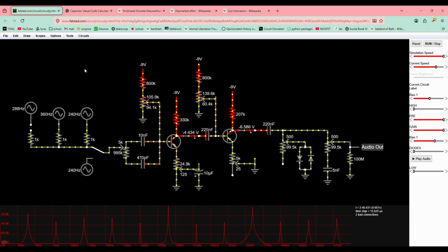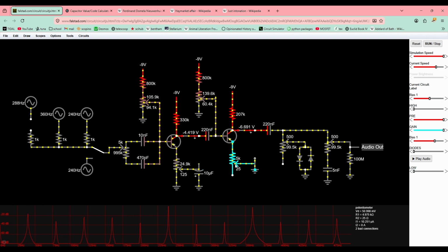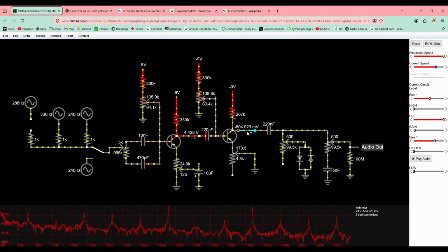So here we are back in the editor. In a bit you'll see me assemble this circuit. We have our preamplifier here, we have our high pass filter here. I set up a thingy that allows you to play a chord or a single note with this switch. This is a power chord. Here we have a second amplification stage, and here I'm not using the capacitor trick because I want my gain to be able to go up to the point where it completely goes over the voltage limit, so you can get that really gnarly zappy sound.